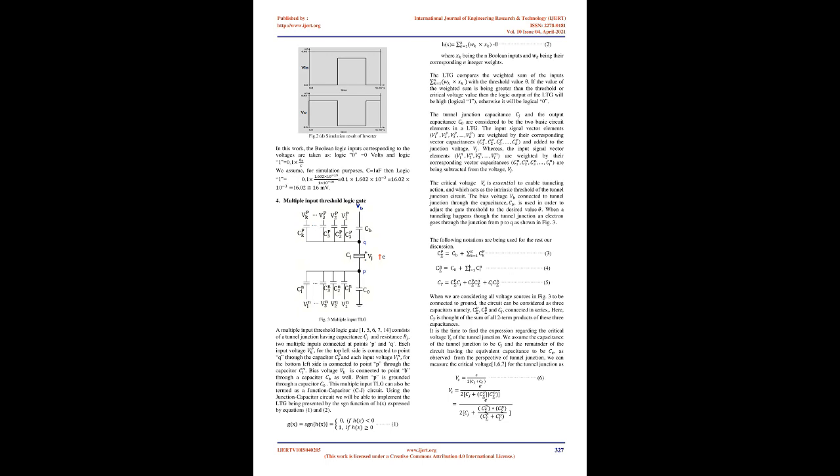The electric potential of the island can be tuned, i.e., increased or decreased, by a third electrode called the gate, and the gate is coupled to the island through a capacitor. An extra capacitance, one which is intentionally connected to the island for the purpose of manipulating the gate voltage, is the input. The drain, source, and gate voltages may be marked by Vd, Vs and Vg, respectively.